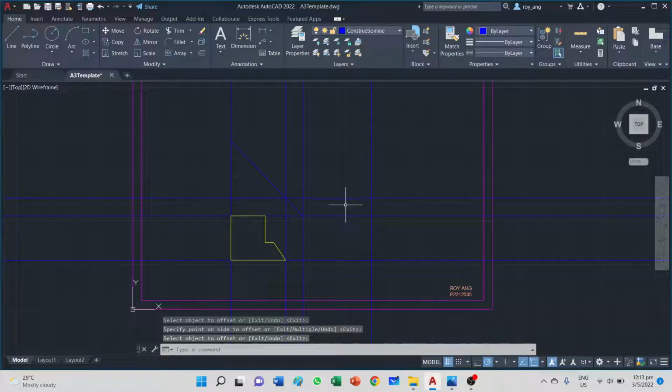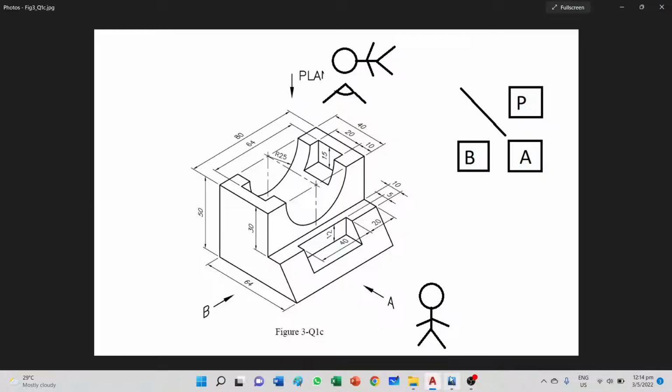And the next question is, what is the width of my plan view, or the breadth of my plan view? Okay, it's not known here. And if you look at the drawing, when you float up, the width of your drawing for the plan view is 64. The length would be 80, so the length is already drawn. It's the 64 that's not drawn. Now you can do it two ways.